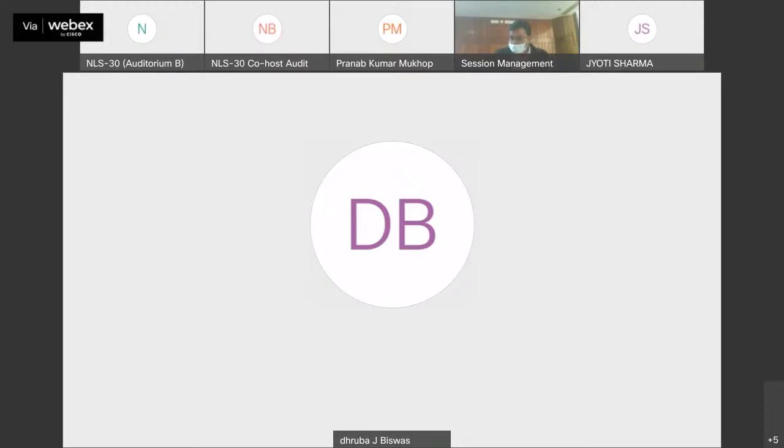So for your line width measurement, you bifurcated the output into two and then heterodyned it. Yes, sir. What was the result in time? How was the beat frequency changing? The output from this heterodyne detection setup is based on these beats, and by analyzing the beat spectrum, we got the information about the line width of the laser.